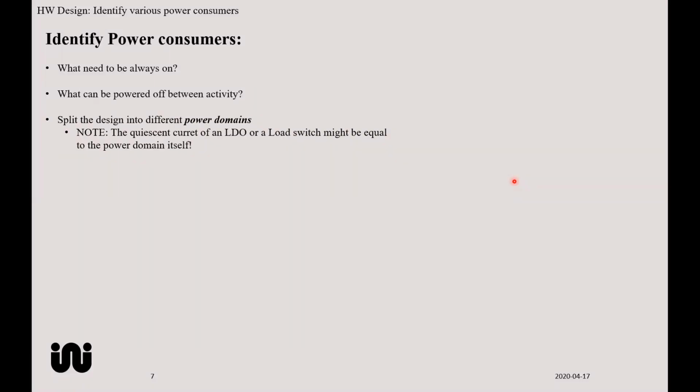Split the design into different power domains, which is smart. If you have a sensor node with multiple sensors, you might not have to monitor each sensor at the same frequency as any other sensors. Temperature, for example, is a slow-changing thing, while other sensors may need to be sampled much more often. They should then be treated on different power domains, rather than keeping all the sensors running when sampling only one.